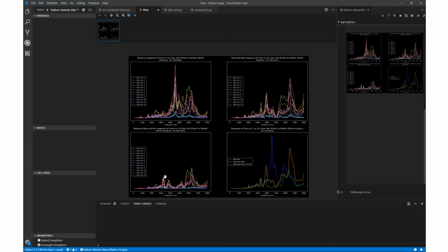This isn't obvious. It wasn't obvious to me. Normally you'd think that a rigid gear blank would be the best. But making it thinner reduces the mass and increases the compliance. This affects the mesh force and transfer path. So it reduces the acceleration to the casing. The energy is caught up somewhere internally in the model. So for me, I think it's important to have a product like MASTA so that you can get this sort of result, because you can't just rely on intuition.